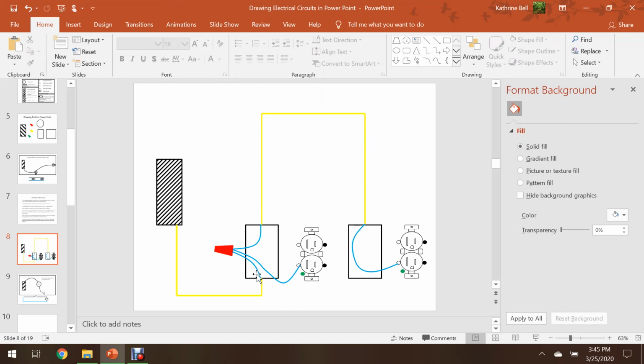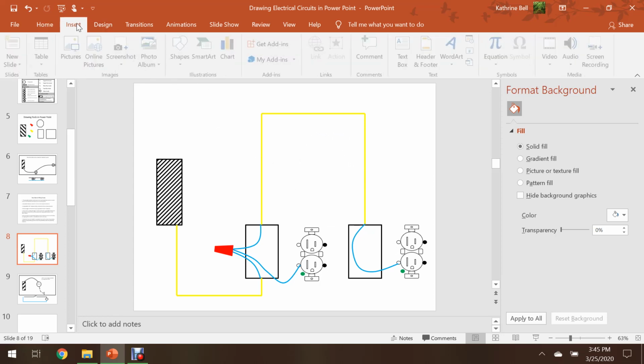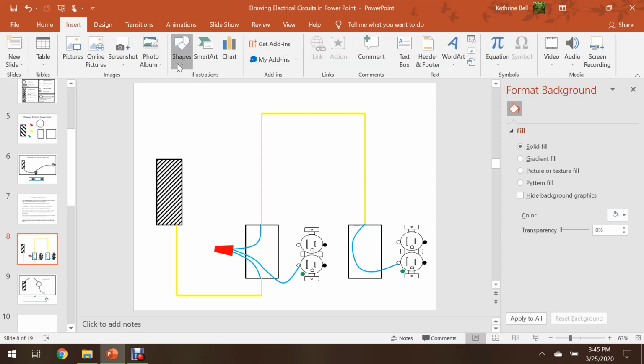All right, we've got to carry our ungrounded conductor or our hot wire. And this time we're going to use the terminals that are on the duplex receptacle. Now when I do this, that is wiring this receptacle in series. But as long as that tab that exists right there is intact, then this entire circuit will work. There's nothing in the National Electrical Code that prevents you from using the terminals.